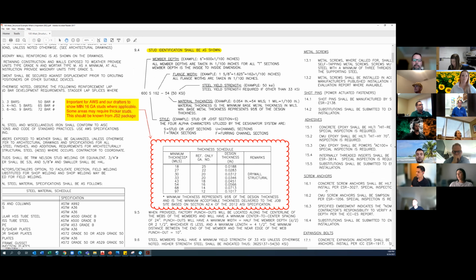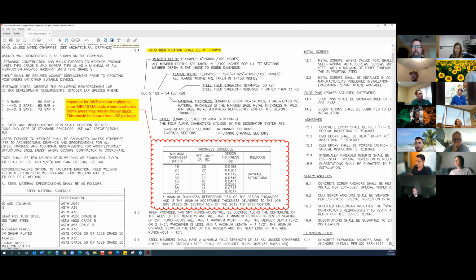So this table here again is the thickness schedule of the studs. This is again something that we're all familiar with, but you can see that the person who's going to supply the studs, their thickness can vary throughout the entire project. And anywhere we attach, it is typically going to start with a minimum of 16 gauge. And I can guarantee that if you don't communicate this up front, you're going to have 20 gauge or even 22 gauge that the stud sub is going to carry, because he's going to carry obviously the thinnest he possibly can because it's the cheapest for him. So we have to be really careful with that. And then in places where we need thicker studs, we need to make sure that we tell the contractor that. So this is an important table.